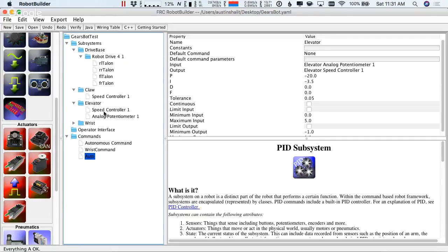What it is is a variable resistor. So you turn the thing, and this little thing turns around a little track of carbon that changes the resistance through the little carbon trace. And so you can measure the voltage from the potentiometer, and as the resistance goes up, the voltage goes down, or something, and then you can take that voltage and it's proportional to the angle of the knob on the volume control. And if you connect the knob to the wrist joint like this, so that the potentiometer is here, then it measures this angle, and then you can write code that drives until it gets to the right angle. And so that's how you use a potentiometer for that.